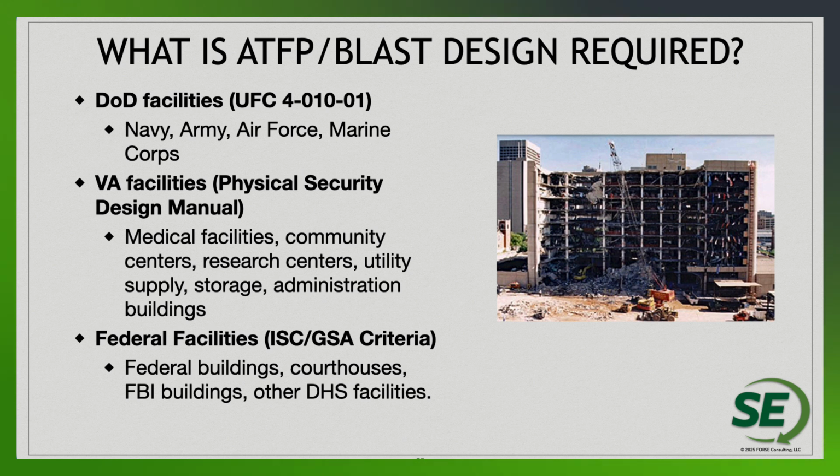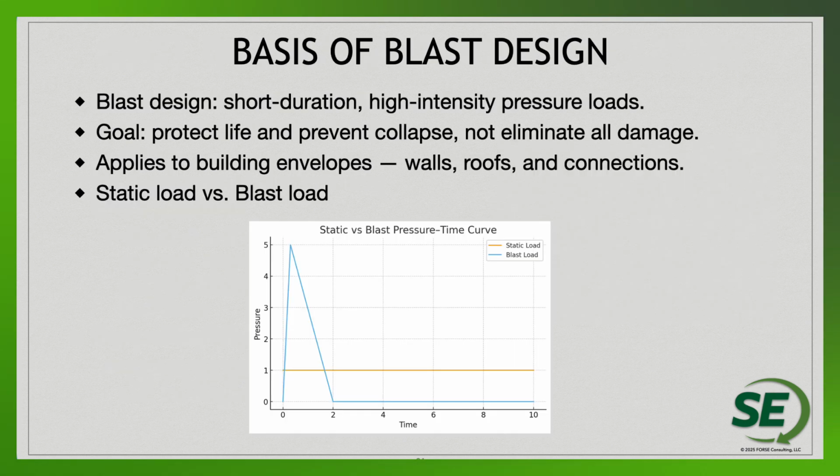Blast design requirements show up across multiple federal agencies. So we've got DoD facilities, VA facilities, federal facilities, etc. But each of these mandates different defined levels of protection for the building envelope, including masonry walls. It's important to note that in practice, we mostly work under the first category, which is the DoD UFC framework, because the others are more specialized and apply to narrower facility types. So the standards from the first group are the primary basis for most blast-resistant masonry design work.